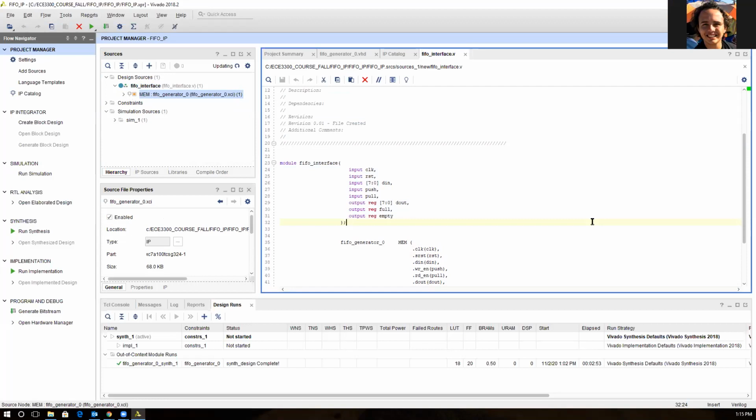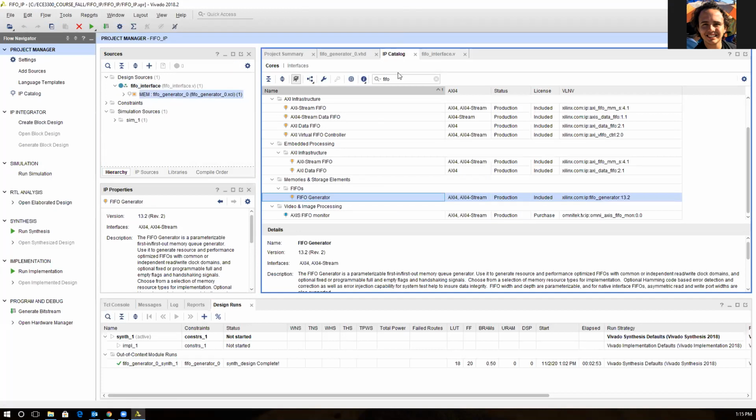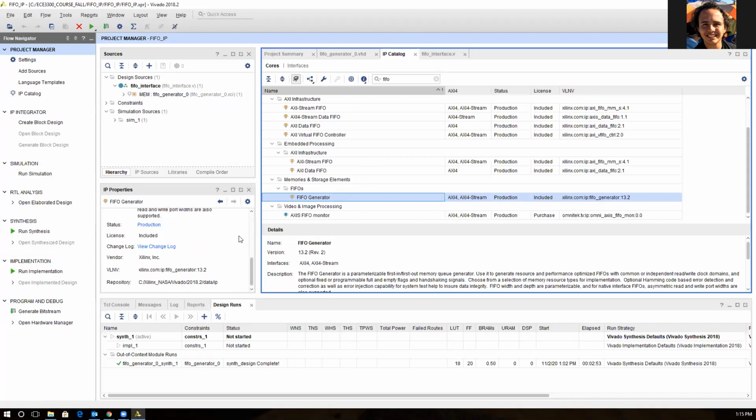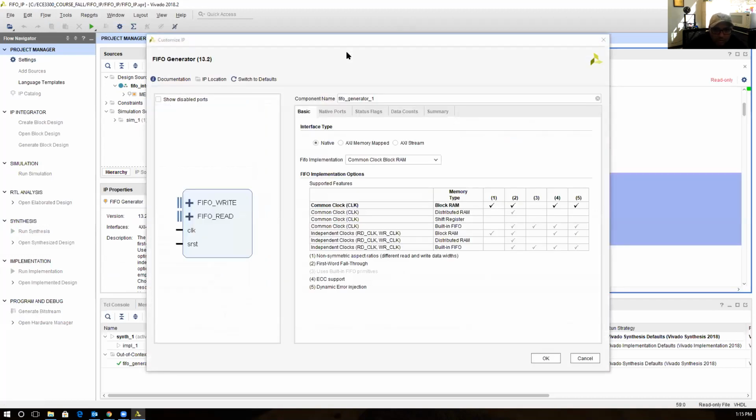I have a question about the first steps you took to make the IP. Yes, sir. You went to the IP catalog and then you just generated it from there? Yes, IP catalog. I typed FIFO in the search and I found the one I'm looking for. And from there I can move forward. I know there is a way to generate it immediately as Verilog, but it seems that I have some problem with my interface. Can we get here by going through create block design? Yeah, I can click again and see. See, it takes forever, it's not even opening. Here it's open. Go ahead.